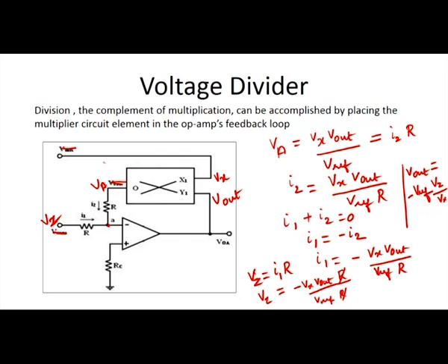Whatever the voltage given at this input terminal of the analog multiplier divides the voltage given to the operational amplifier at its inverting input terminal. So from the circuit, you can see that the output voltage is Vz by Vx, both given externally to the entire circuit.